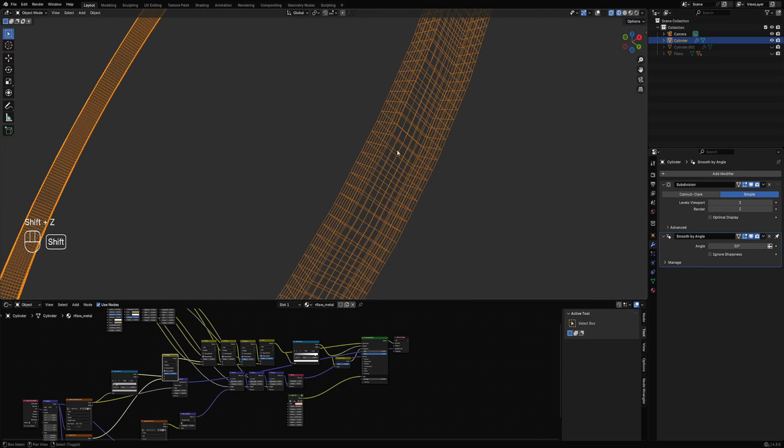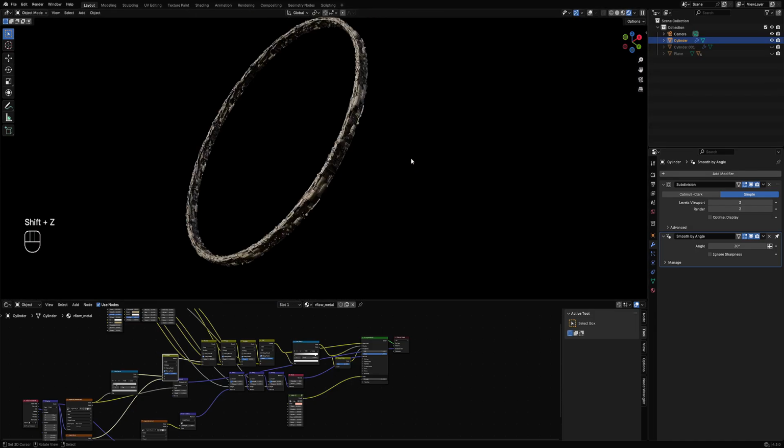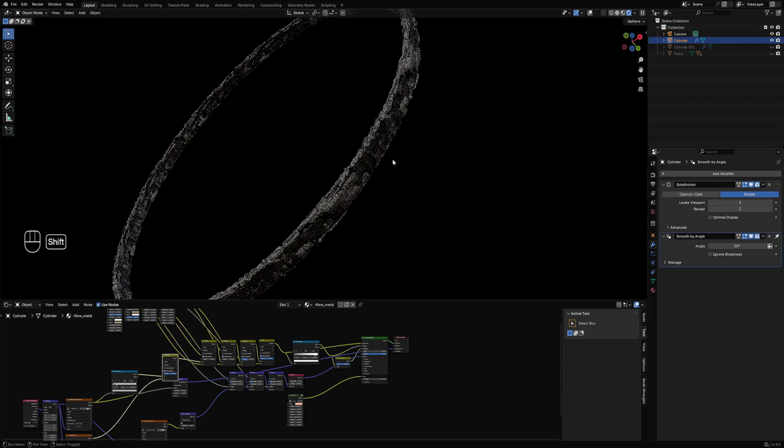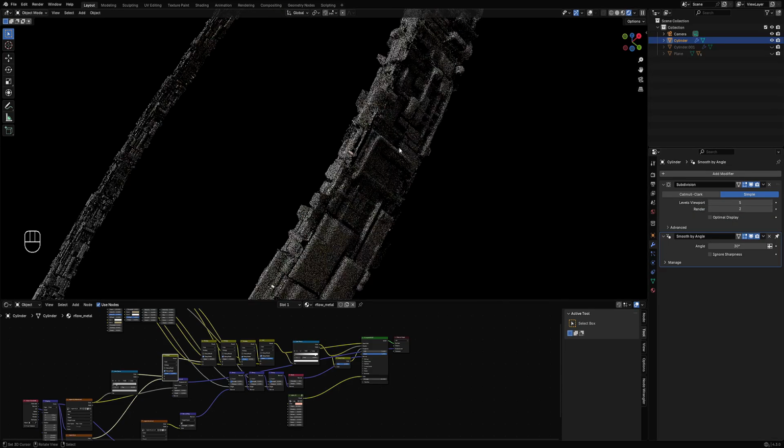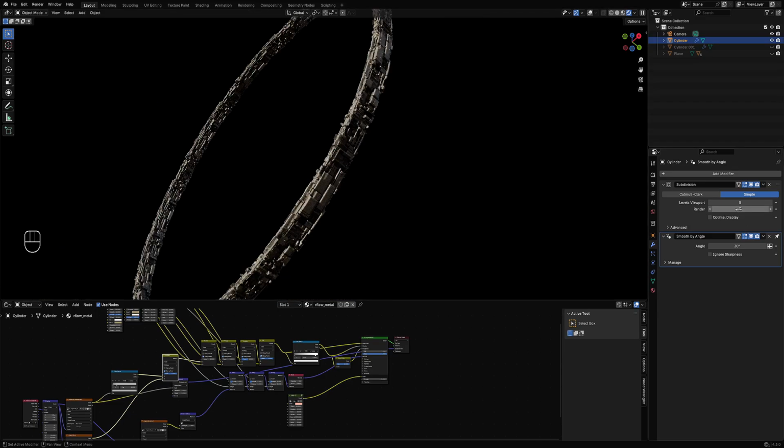And this is the resolution. And the closer you go, or you render this in your scene, you can just increase the resolution to increase the detail, the fidelity of the detail. And also, when you're ready to render this, you need to match the render values of the subdivision to the levels, or the levels viewport value. Okay, it's because when you render this, you might render this at 2. So this is what it looks like at 2 subdivision.